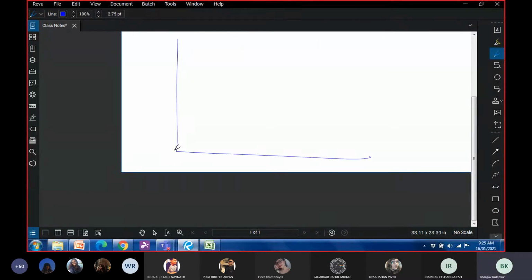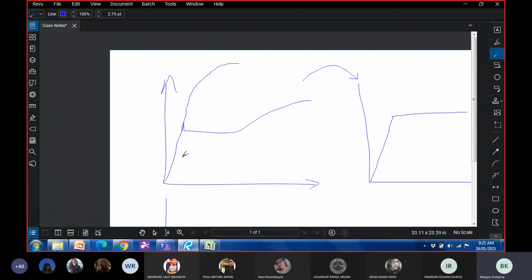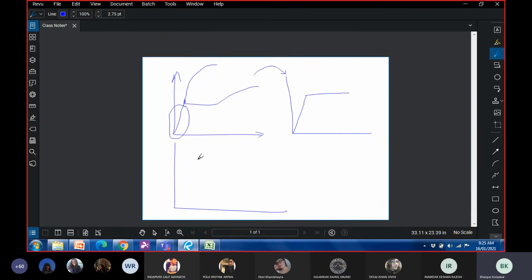This is because, as you've seen for steel, irrespective of the grade of steel, in the linear elastic portion the curve remains the same. And therefore there is quite a lot of certainty as regards the behavior of steel when it is in the linear elastic region, and there is no reason for us to divide it with any partial safety factor.